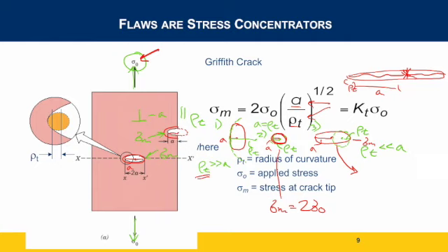So when they fix a windshield, obviously the easiest way is to take the whole windshield out and put in a new one, but they can also fill the crack with a clear polymer material to fill in the void. But that's not all they do, right? Because if I just fill in the void with a polymer, I'm not changing the size or shape of the crack, and the crack will just keep growing. So you'll fill it in, it'll be good for a day, and then a couple days later it'll grow even bigger. So what they do is they drill a hole in your windshield at each edge.